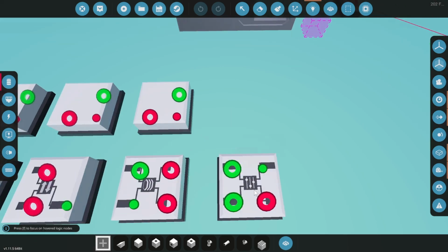Okay, so we look at the inputs. We have the set point, which is the desired value to correct the process variable to. We have the process variable, the current measured value of the system. And then we have the control output, the output computed by the controller. And then you have the active, which sets whether or not the controller is active. When inactive, the stored values are reset. Meaning when you turn it off, it just goes to 0. That's all it does. So in other words, it shuts itself off.